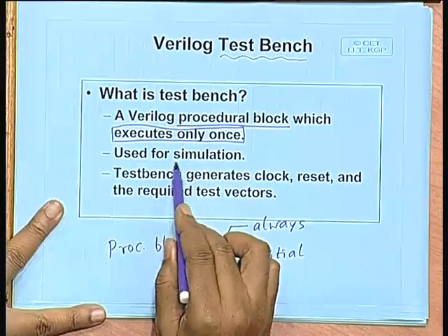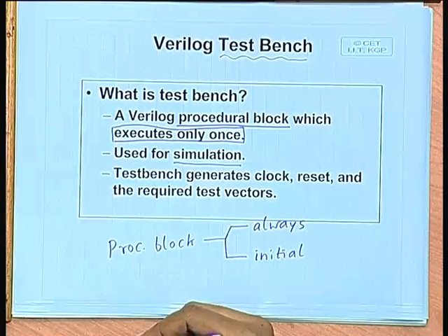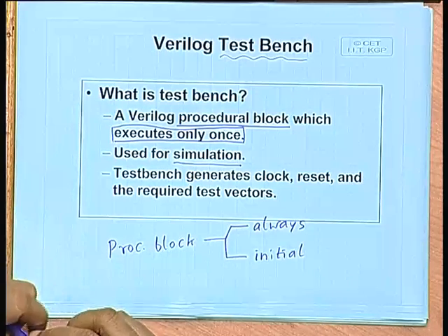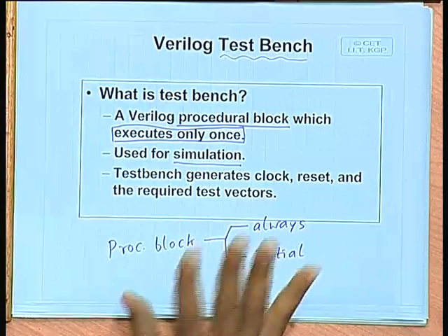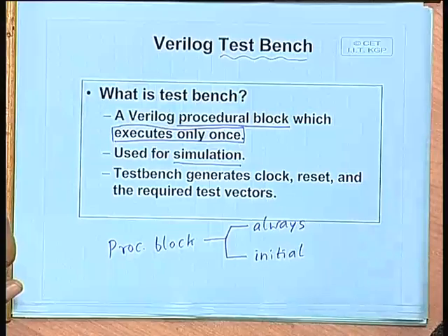Okay. Test bench is obviously used for simulation, you are not using it for synthesis. Test bench is something which is simply used to check whether another design you have made is correct or not. So, a test bench can contain some constructs which cannot be synthesized, like you can have a statement read from file, you can output something on the screen, you can specify explicit delays using hash, those things you can do in a test bench, right.